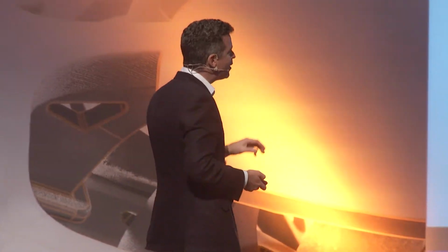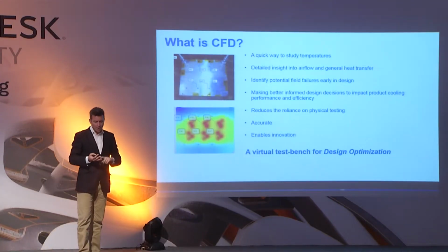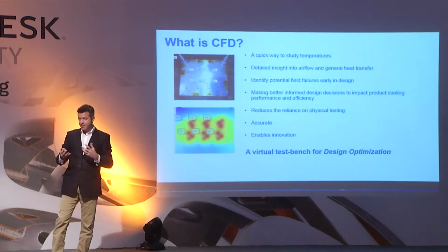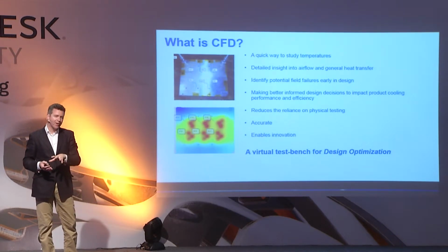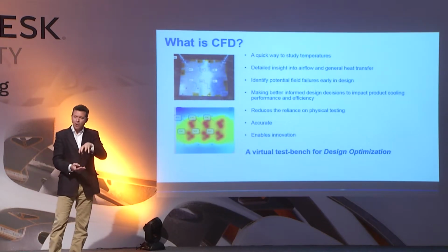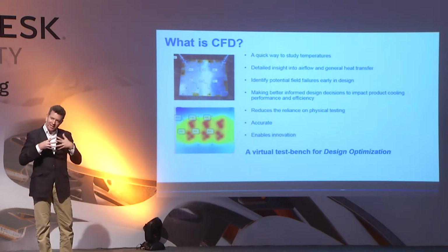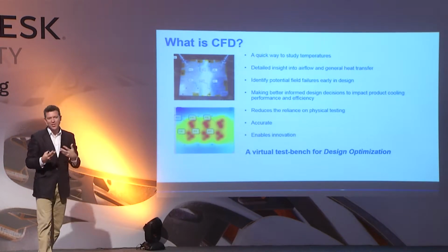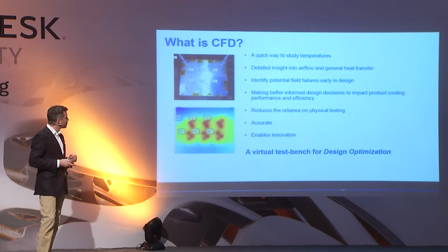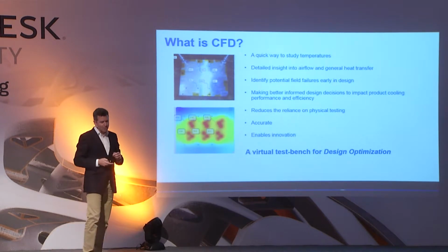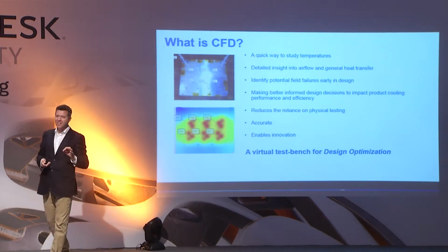We can also get a very clear picture of why the heat is at a certain temperature, and that's often down to airflow. If we channel more airflow over hot components, we make them cooler. So heat and airflow are connected together. So being able to visualize this is very, very important. So this way, as an engineer, if we can identify problems very early and get some guidance on how to improve the design, this is hugely valuable. And it doesn't need to be something that's driven by a specialist.